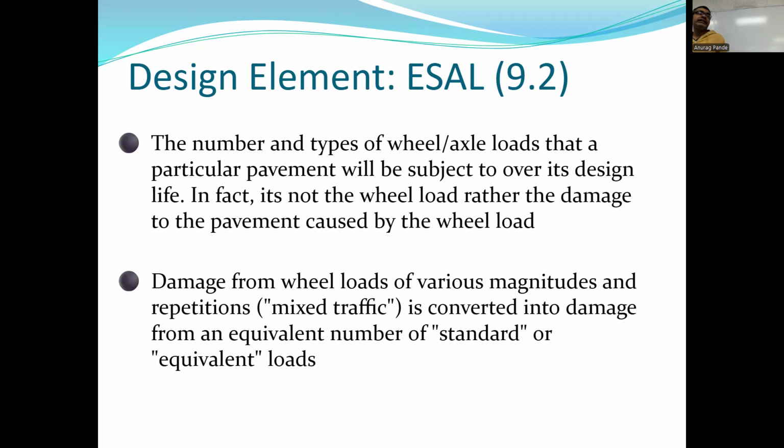The design element is called ESAL. ESAL stands for equivalent single axle load, right? So basically what we do is we look at the traffic that's going to be on the road, and we convert that into how much of an equivalent standardized single axle load that traffic is going to apply to the pavement. And then we use that as our design criteria. If you have higher ESAL, you'll need thicker pavement.